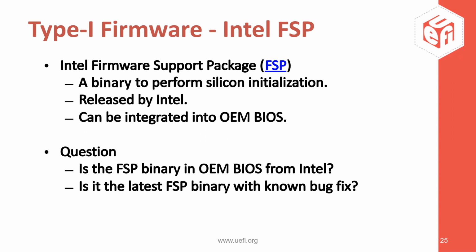Intel Firmware Support Package. So the audience may or may not know the Intel Firmware Support Package, or FSP, is a well-defined binary object that runs on the host CPU that's responsible for some basic initialization, including the memory controller, system fabric, but it's really scoped to the system on a chip.